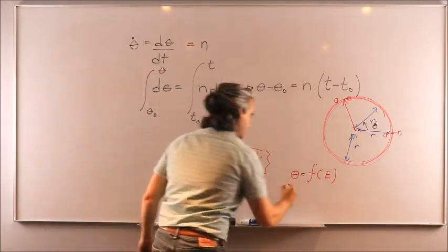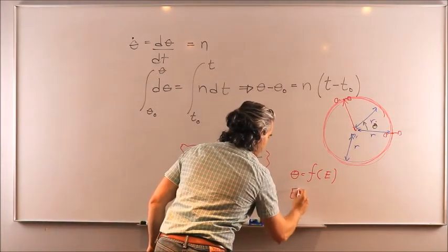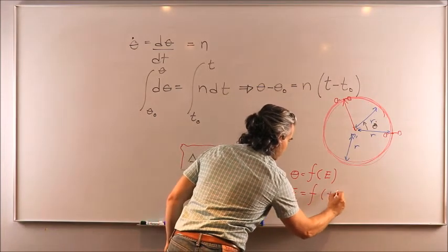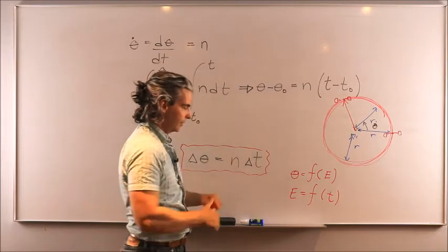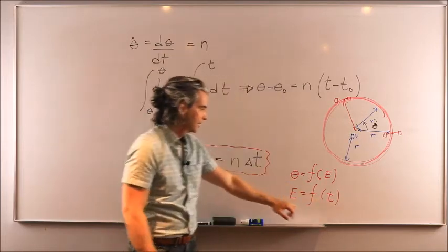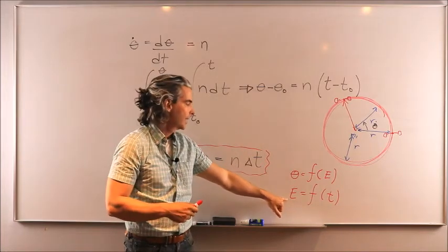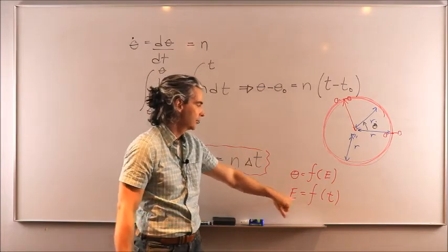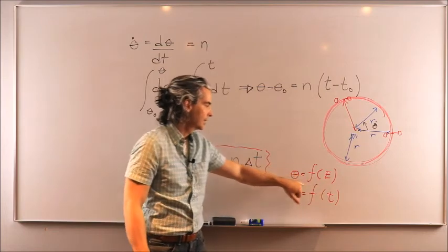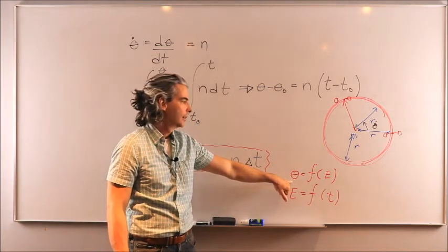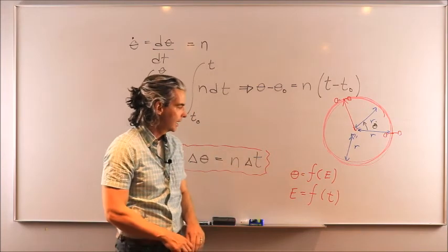And then as a second step, we'll have to relate the eccentric anomaly to a function of time. Okay? So we'll say, okay, in 45 seconds, this is how much eccentric anomaly the position vector covers. And then from 45-degree eccentric anomaly, how does that translate in terms of true anomaly? All right? So this is what we're going to do in the next lecture.